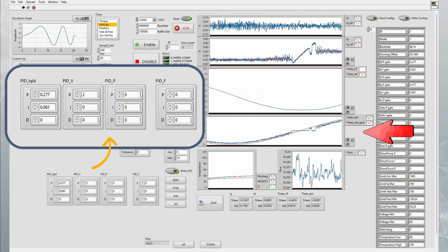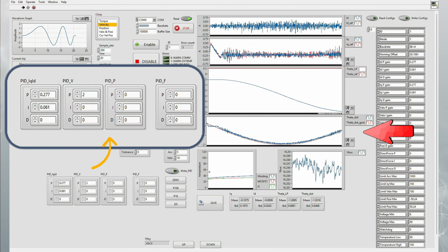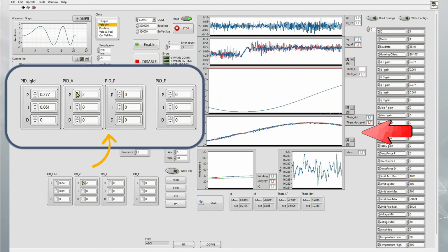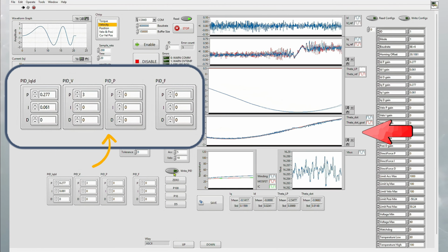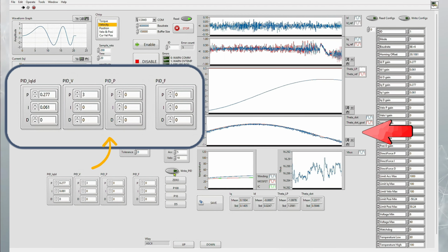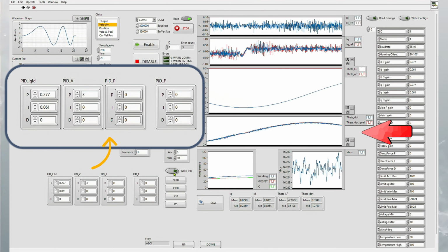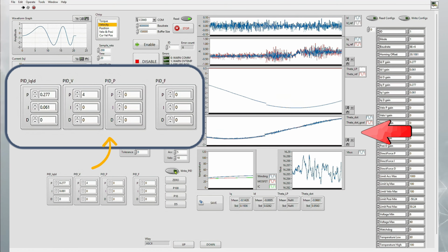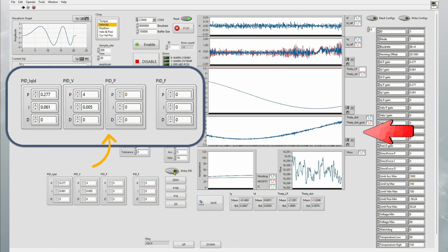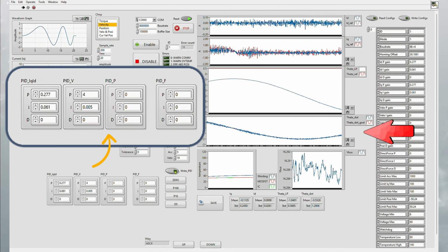In the velocity tracking plot, you can observe that the initial tracking performance is relatively poor. As we gradually increase the velocity loop P gain, the tracking accuracy improves significantly. If a steady-state tracking error persists at peak velocities due to internal gear friction, introduce a tiny fraction of I gain, typically between 0 and 0.01, to eliminate the residual offset.